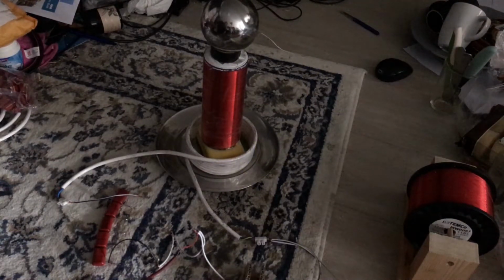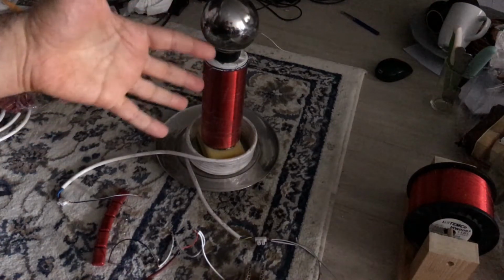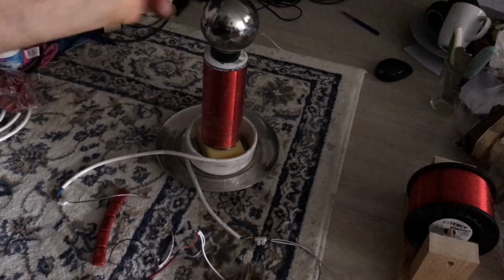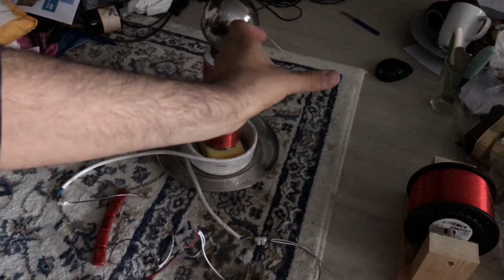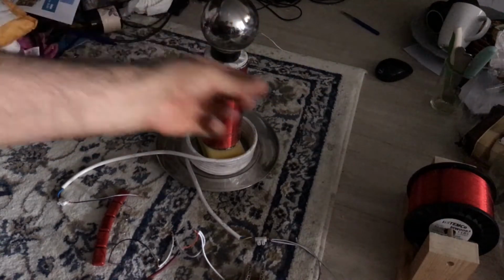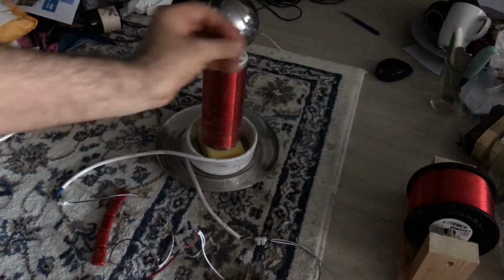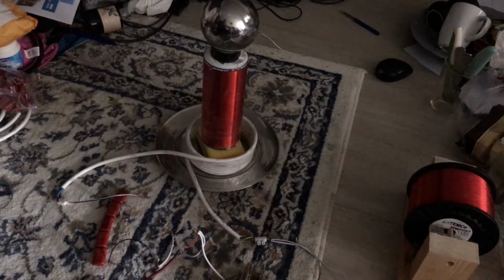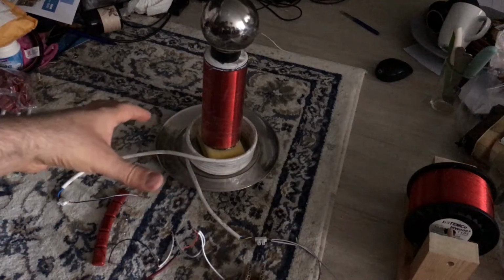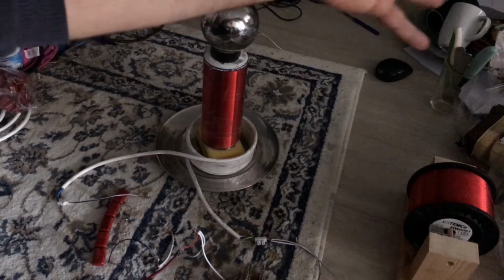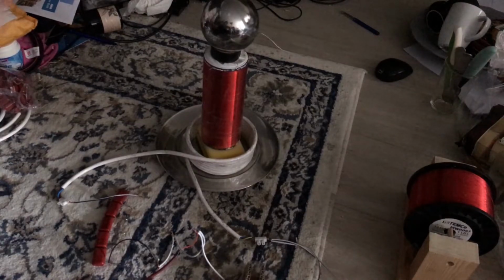And the repetition rate of discharge is very low because the power source is very weak. If you would have a stronger power source, basically these discharges would happen more frequent and the ionized air will stay in place, so the next discharge could use that channel and actually propagate to a larger distance. Alright, so now maybe I will connect this one to a powerful source, and then we can see what happens to the output discharges.